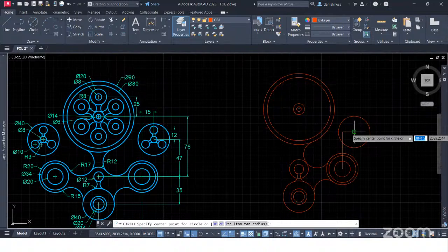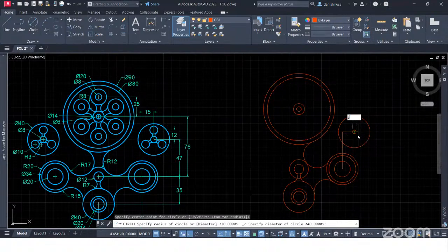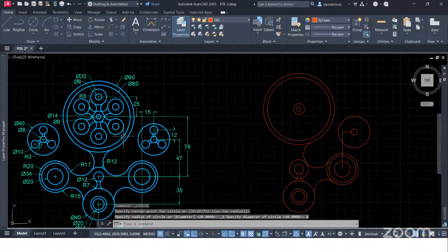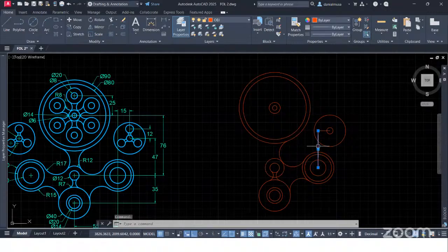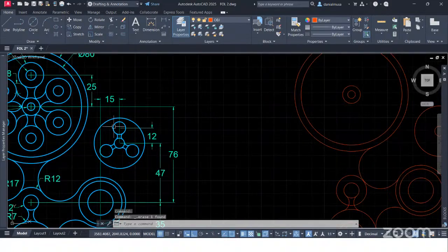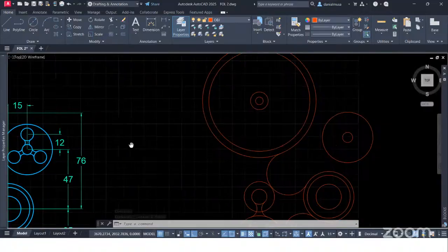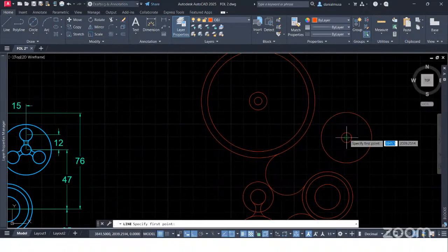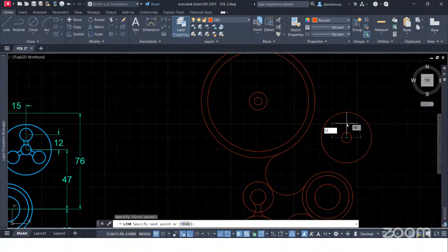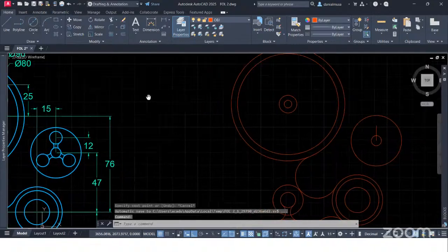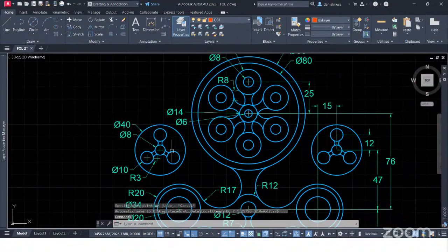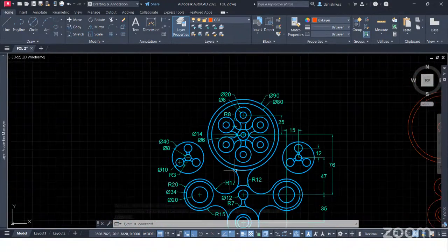Also, so we can just remove the line again. So we need to draw the circle here at 12. So also draw a support line, 12, and let's see. So the circle is in diameter 10.